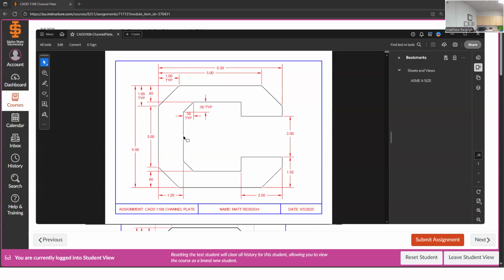We only get a single view of this, so we don't understand any depth of it whatsoever. But a bevel and a chamfer are kind of the same terms. Chamfer is what the command's called in CAD, so I think that's a good one to think about, how to put these on. I think I'm going to show you the chamfer command with this one. Rather than worry about how these turn back this way, I think I'm going to draw this as a full rectangle, and then apply the chamfer command and have it do this for me automatically. I'll show you how that works. And it's probably something I can do to the inside too, chamfer that.